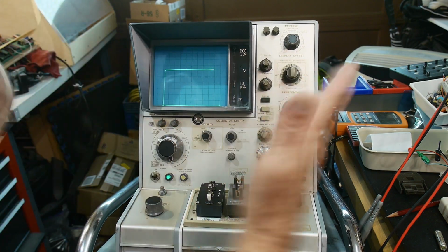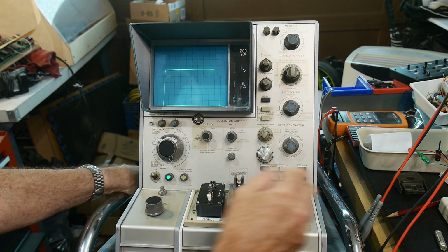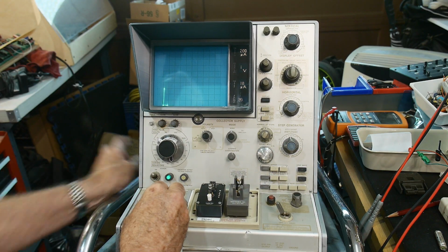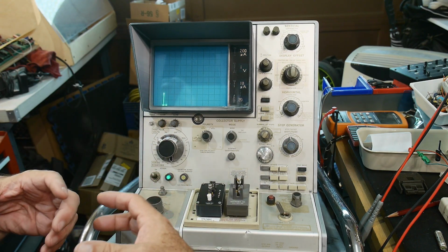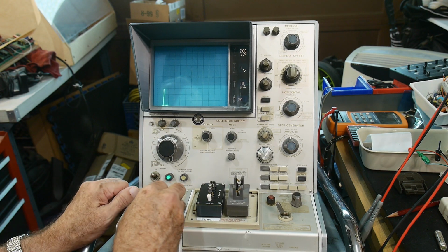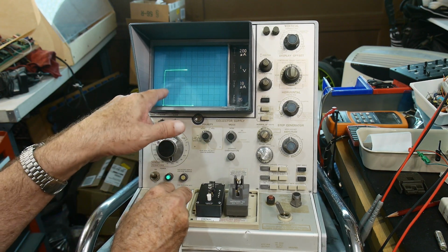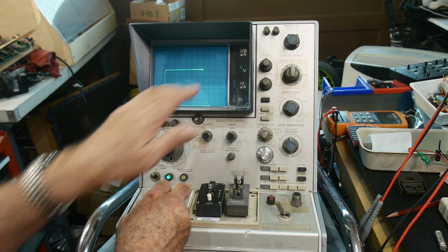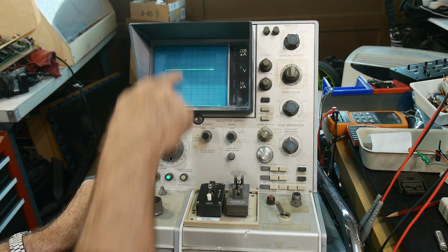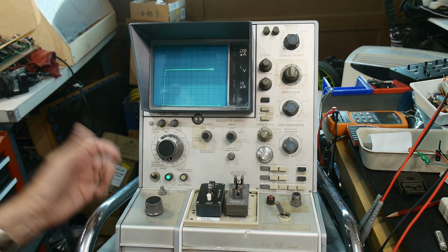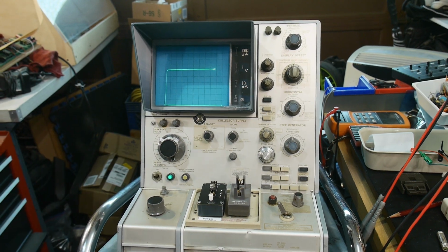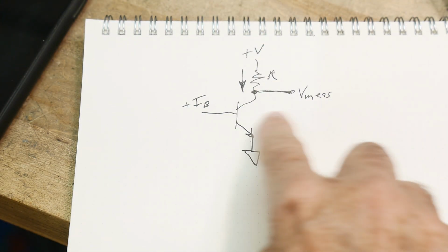But why is there a curve? Why is this curve here? Well, that's because the transistor doesn't work very good at small voltages. You need to have enough voltage to make it work. And then once you have enough voltage to make it work, it's always about the same, okay? But how come it doesn't go all the way across? Well, that has to do with the resistor that we're using, okay? Remember I said that you could choose the voltage and choose other things.